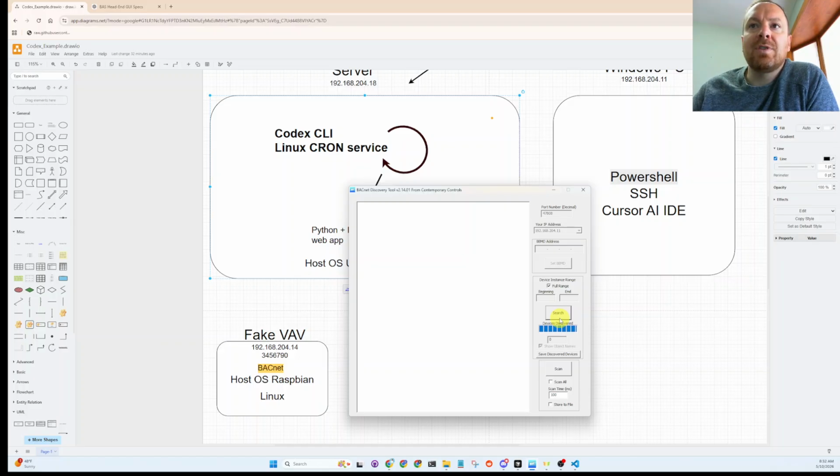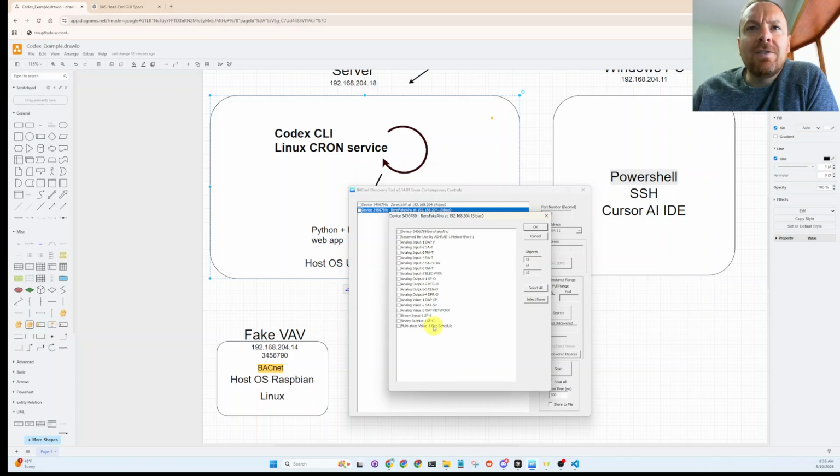So I'm actually going to put that into the spec. If you see this as outside air network, it's a writable BACnet point. What is common is that data is written from one device to the other device through writable BACnet points.